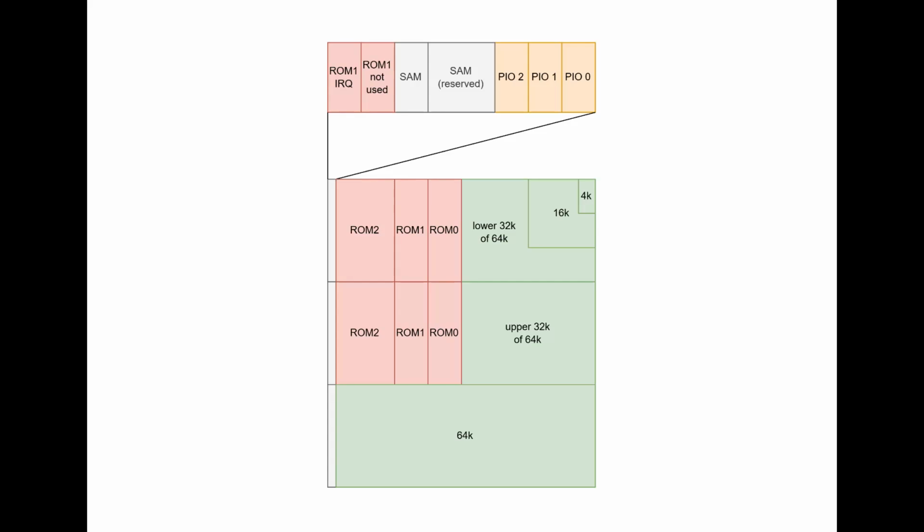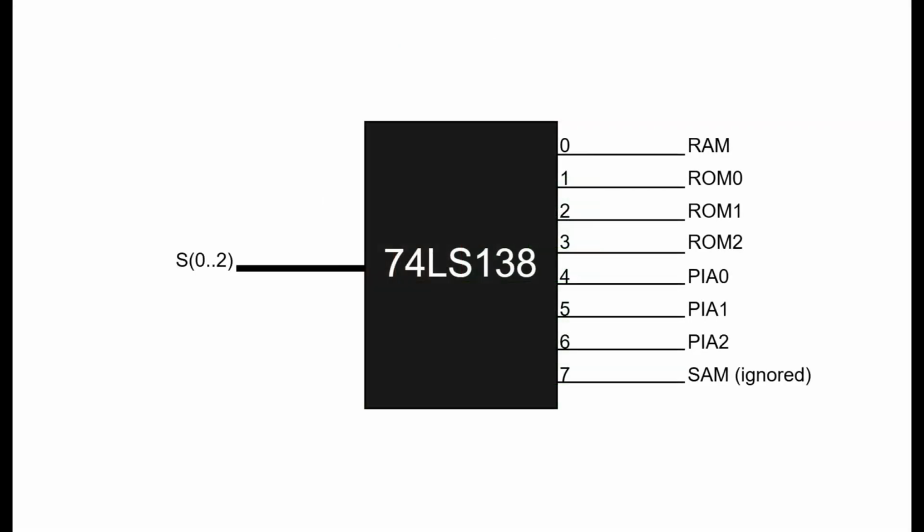The RAM access is normally further complicated by a configuration for memory size, either 4K, 16K or 64K of dynamic RAM, or 64K of static RAM. For my purposes, the answer is always 64K of static RAM, so this bit of configuration is ignored. The device select is exposed externally as 3 control signals that expand to 8 control lines. Internally, the device select is also used to inform the address-dependent part of the CPU clock.